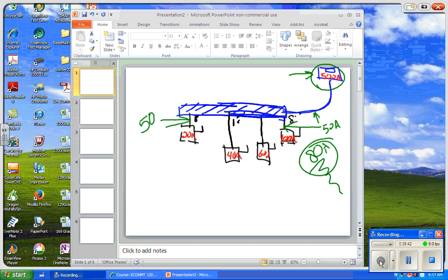Now let's look at the 25-foot tap rule. Now our two center starters here, or disconnects I should say, are 40 amp and 60 amp, right? But they're 12 feet away. They're both not very clearly written. We're saying that they're 12 feet. That means they're not under the 10-foot tap rule. If it's 10 feet and 1 inch of conduit, they're under the 25-foot tap rule. Okay, 25-foot tap rule says 1/3. What is 1/3 of 500 amps?